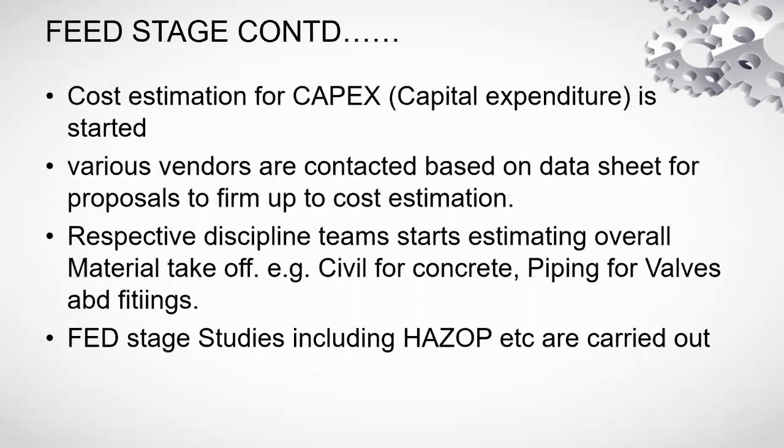Yes, then the next step, which starts probably after a few weeks of start of FEED, is cost estimation for capital expenditure. This is again a very important stage, and I'm sure most of the end user clients have estimated some cost estimates for this plant at the initial stages. But now when FEED has started moving, the cost estimate starts moving from approximation to accuracy bit by bit.